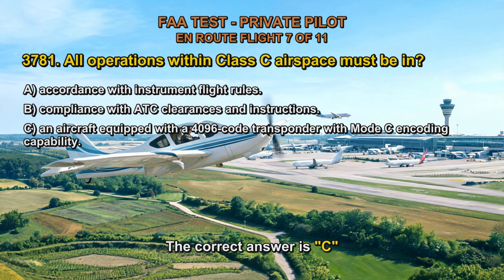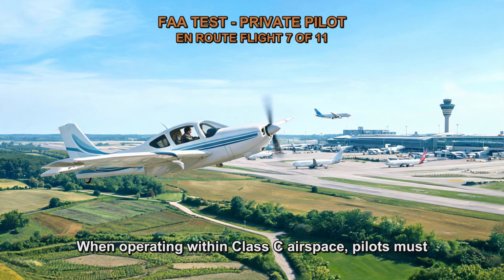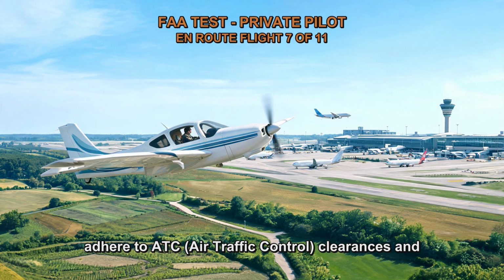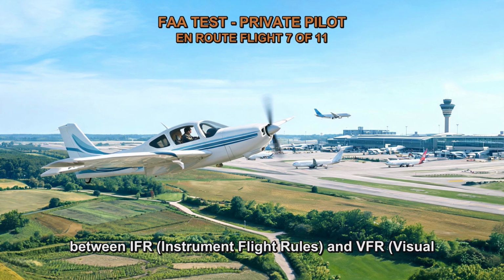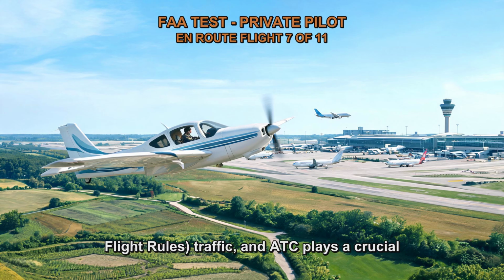The correct answer is C. When operating within Class C airspace, pilots must adhere to ATC, air traffic control, clearances and instructions. Class C airspace is designed to provide separation between IFR, instrument flight rules, and VFR, visual flight rules, traffic, and ATC plays a crucial role in managing the flow of aircraft within this airspace.